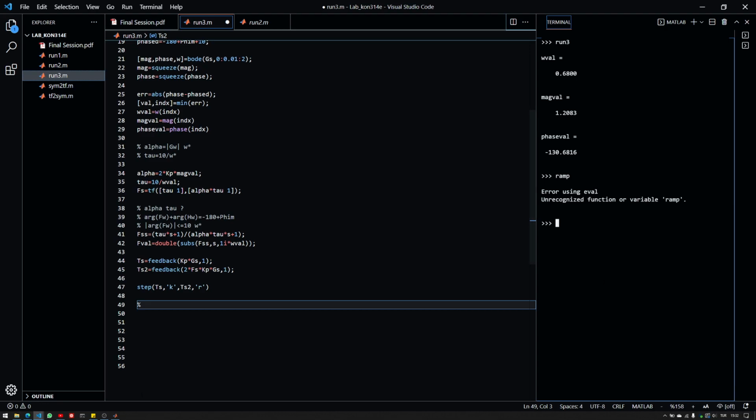Seems like it. So there's no ramp function. You could use LSIM, but I don't want to overcomplicate stuff. But since we deal with LTI systems, I can basically include an integrator, because if I take the integral of the input, the output will still be integrated. It will not mess up.